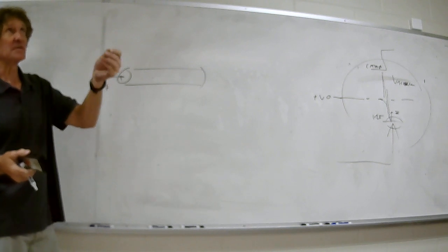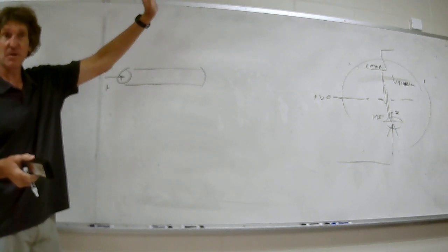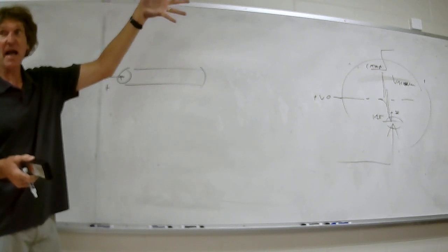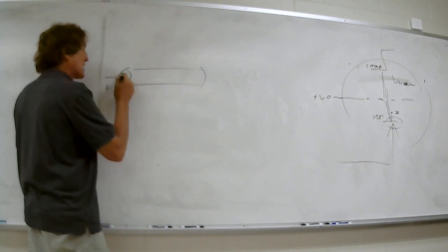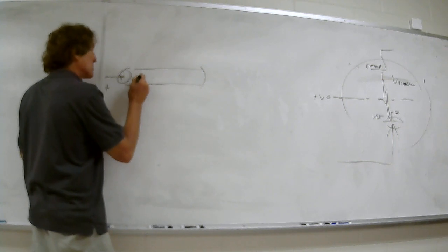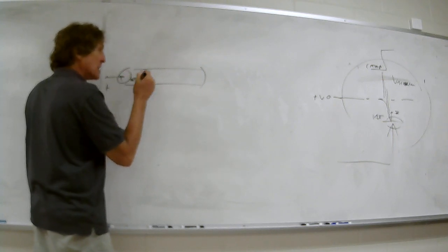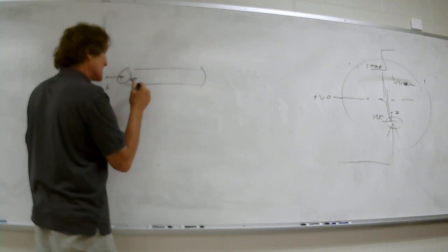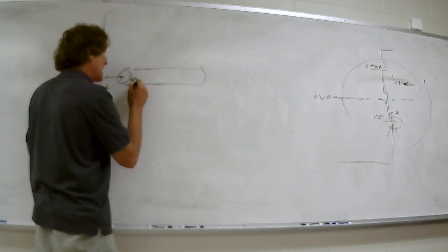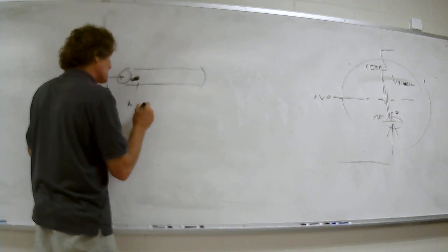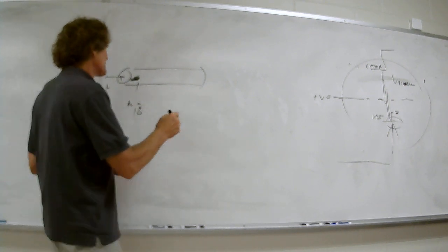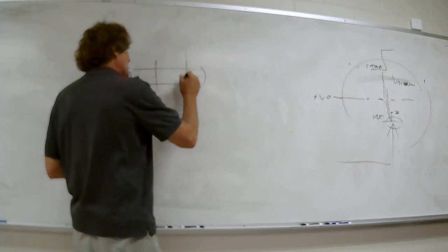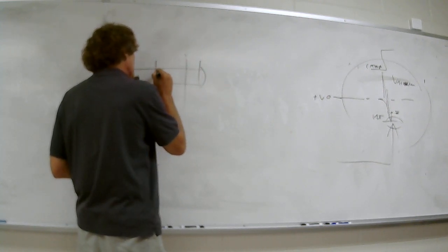It's almost like that stuff they zap bugs with outside, where you've got something that will zap basically every time a bug goes through. Here it's similar with the grid. It comes through, it ionizes the particles, and they're really going to be something with usually a single ionization level, almost always. So it's going to have a given mass to this particle and a given charge Q, usually just one electron distributed. Then it's going to go through and accelerate through a set of grids here, porous grids,